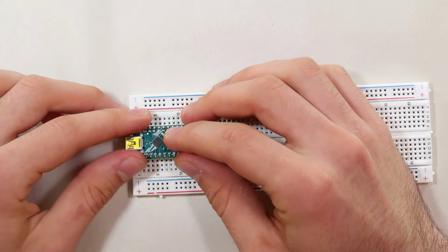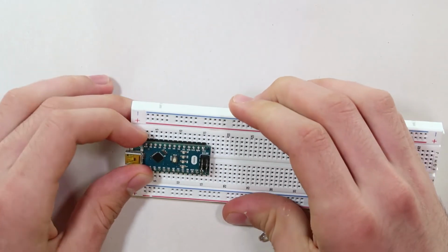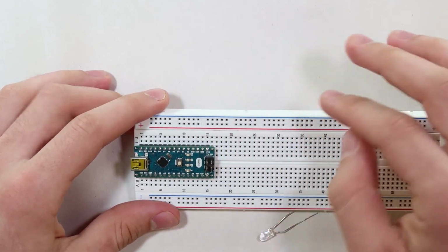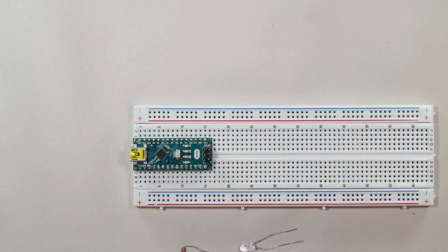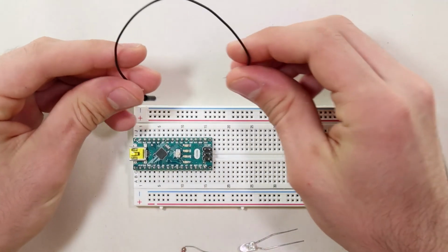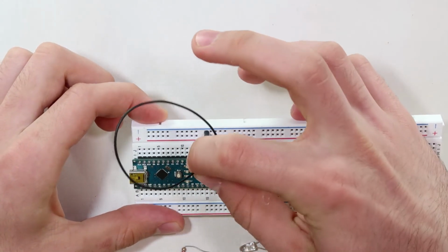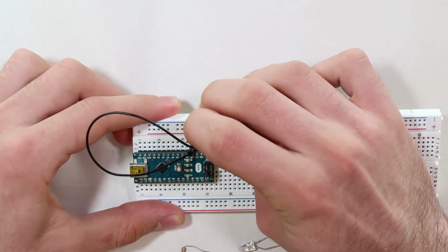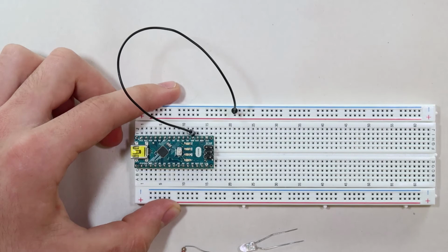So our first step is we're going to connect the Arduino Nano to the breadboard, and make sure the pins on either side of the Arduino are on different parts of the breadboard so you don't run into any issues there. Next step, let's ground. We're going to connect one of these rails to the ground on the Arduino. We're going to have multiple components that connect to ground, so having a grounded rail is going to make our lives easier.